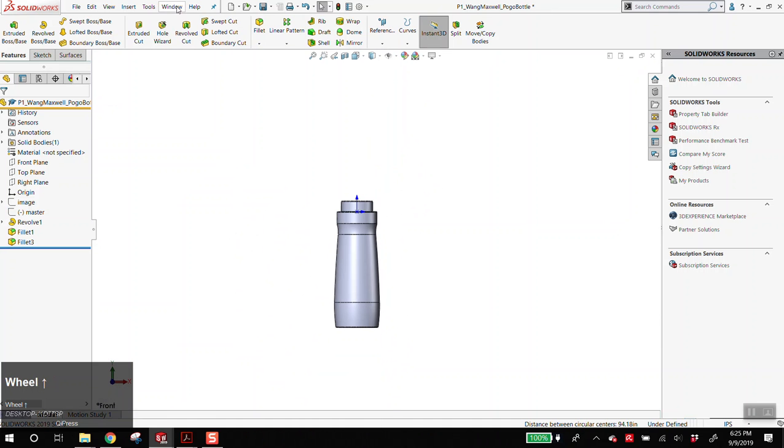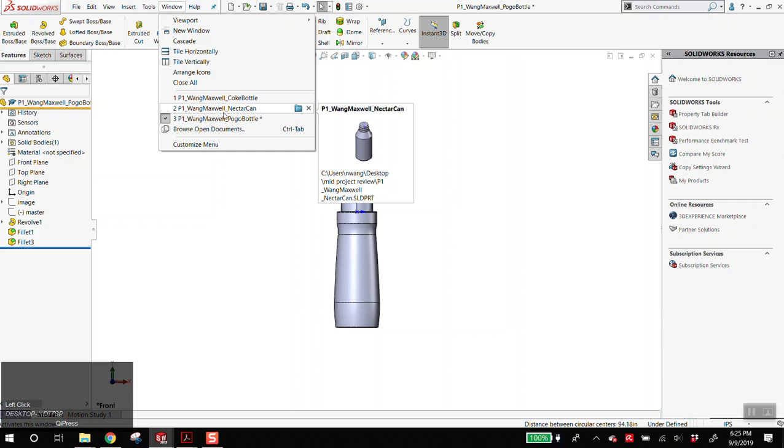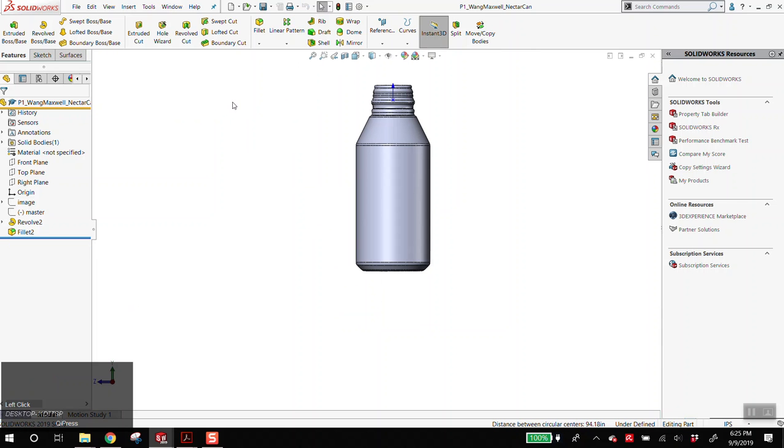Yeah, Max. I would also do the width, but here's the confusing thing. The neck finish, we will see the transfer ring on some of your models. For others, the cap will cover the rest of the neck finish. So I honestly don't care about the neck finish. It's more the cap that I care about. So I would bind the cap's overall width. And you care about the cap too, because when you change the volume of the bottles, you don't want your cap to jump and blow up and fall in the Jenga analogy.